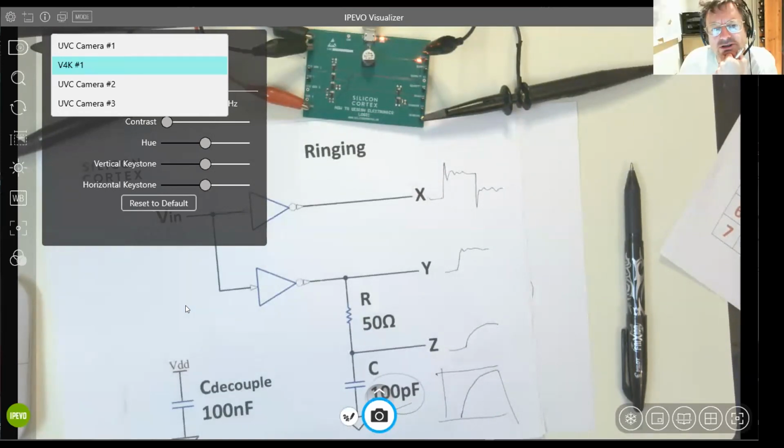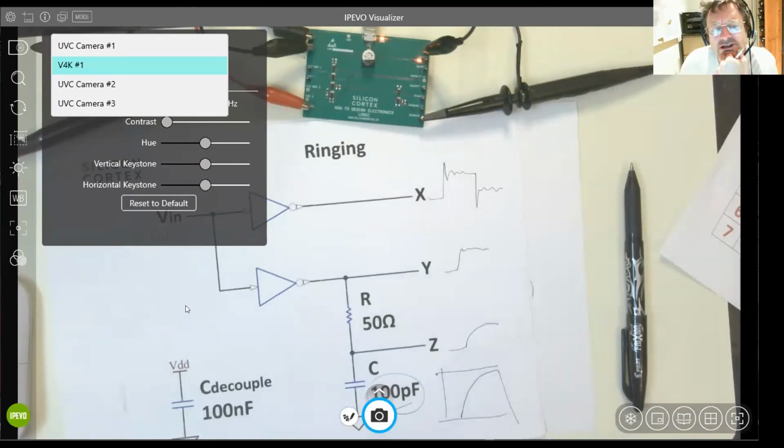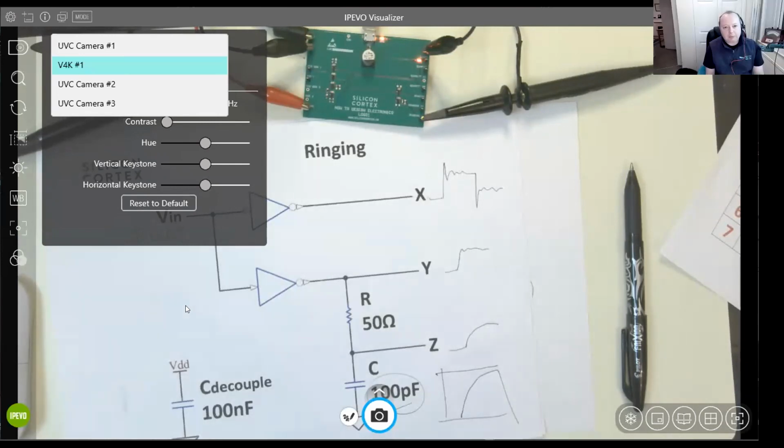So the resistor level that you were using as pull-ups was driven how low? Oh, right. I think we ended up driving that. Well, we started off doing exactly that, creating a smaller and smaller pull-up resistor, and we got down to, it must have been less than a kilo ohm, which is okay.